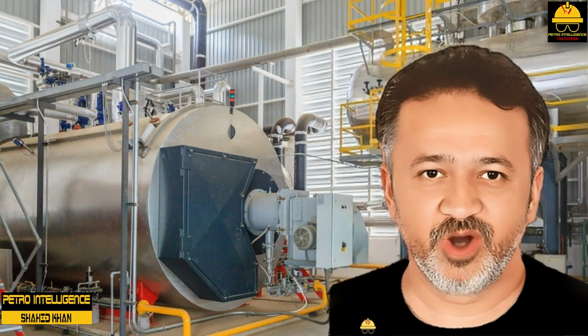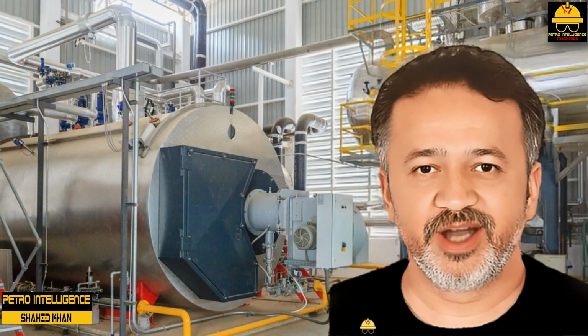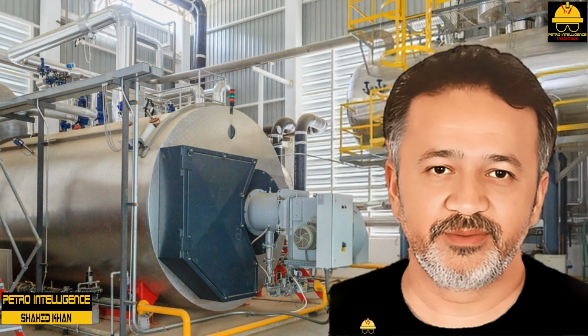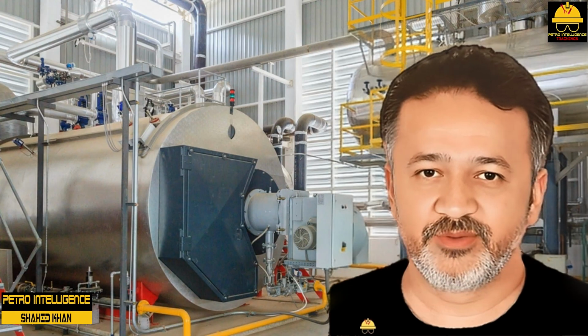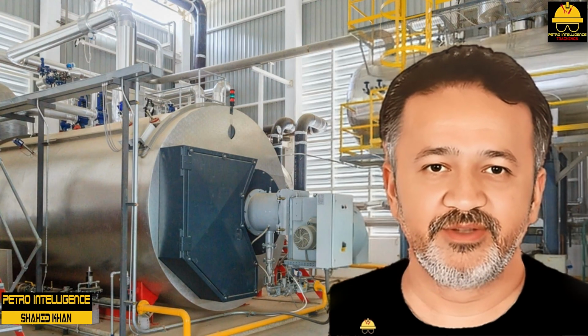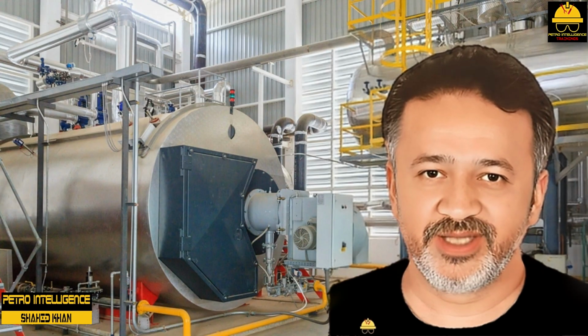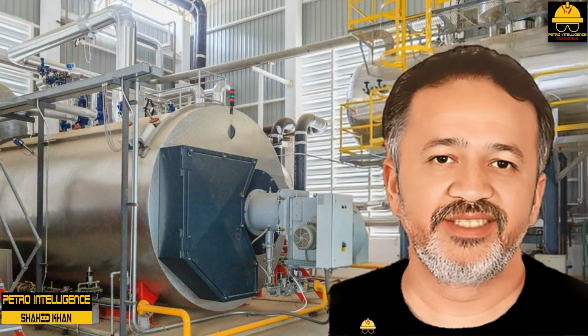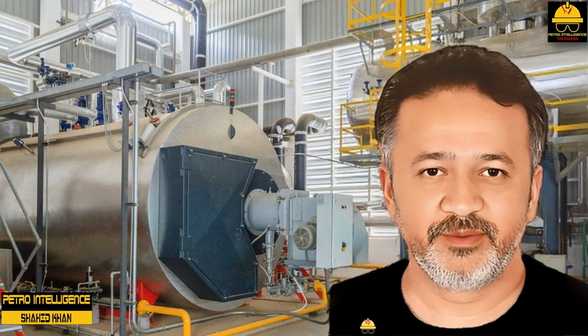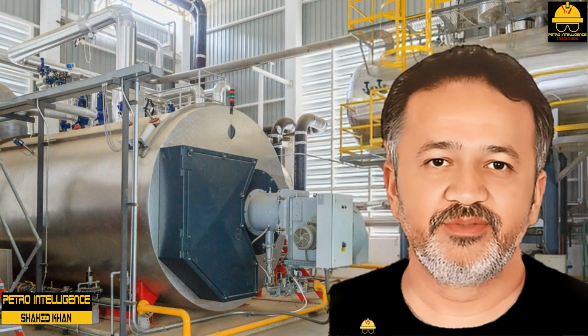To summarize this course, I would say boilers, steam generators, are devices that produce steam. They use a combination of radiant, conductive, and convective heat transfer methods to change water to steam. Factors that affect boiler operation are density differences for internal circulation, pressure, temperature, and water level.